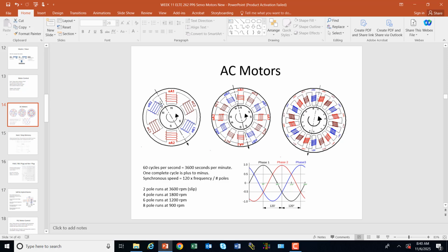But I'm showing 3-phase because we learned that when you've got 3 windings, you get a lot higher performance out of this motor, because you're showing your 3-phase electricity right here instead of single phase. You've got these being 120 degrees apart, so every 120 degrees you're getting a little bit of work out of these. Like I said, you get a lot more power out of it, and better efficiency, all these things, with 3-phase compared to single phase. But we've already been over this in 131, and I'm sure that this makes sense.